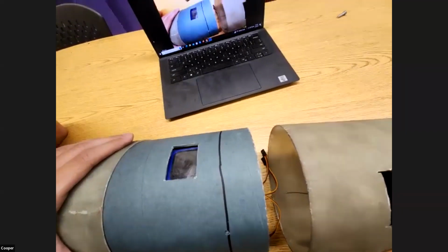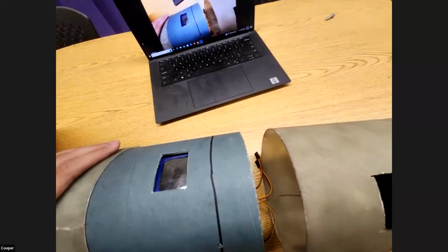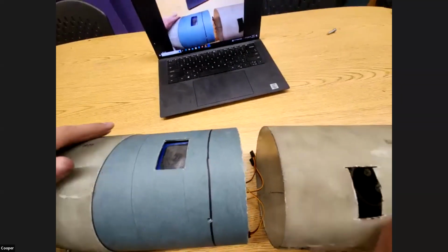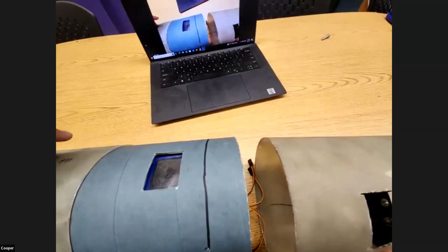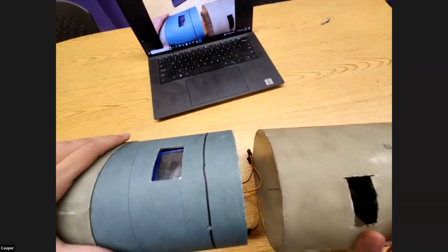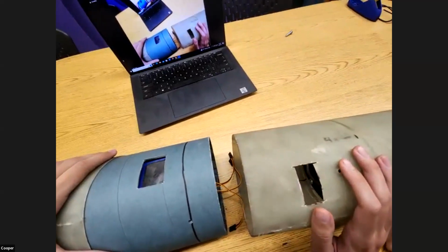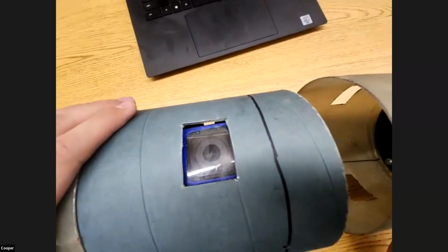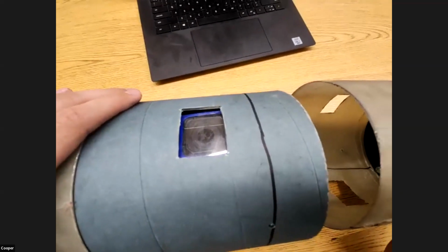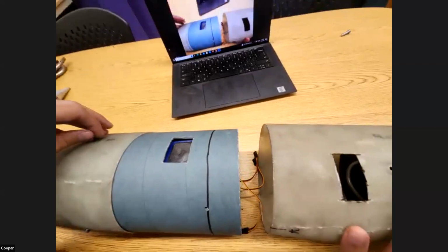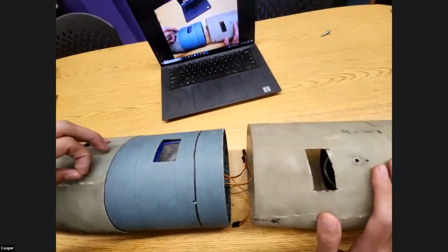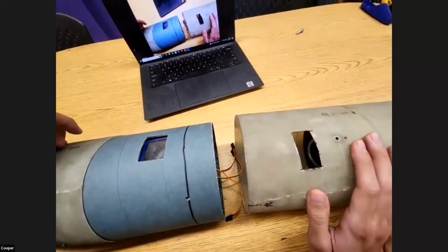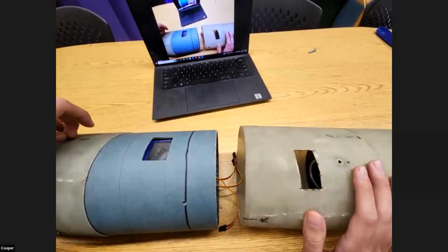Awesome. So we plan to have 7 cameras on this rocket, so hopefully one of them will work. One of them should get you a good view. Excellent. We're going to have 2 Raspberry Pi cameras, 3 GoPros, which is that 360 view. They're each 155 degrees. Because they're 120 degrees apart, we'll be able to stitch them all together into a full 360. And then 2 exterior run cams that will be in the shroud, which is still being developed.